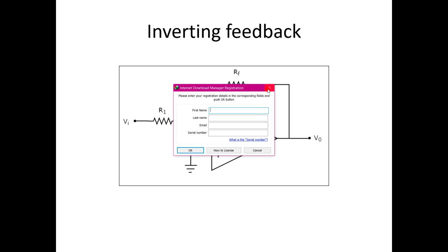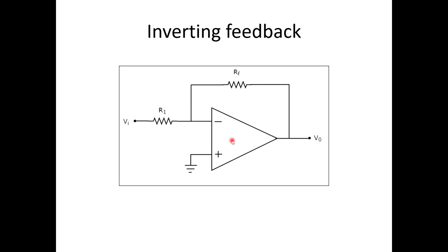The inverting feedback. So the inverting feedback, again, where is the input given? The input Vi is given to the inverting terminal. The non-inverting terminal is grounded. You know this already. Whenever we talk about any of the configurations, say inverting, the input is given to the inverting terminal, and the other terminal, non-inverting, will be grounded. Feedback, so RF and Ri. This path is always there in the op-amp circuits, okay?